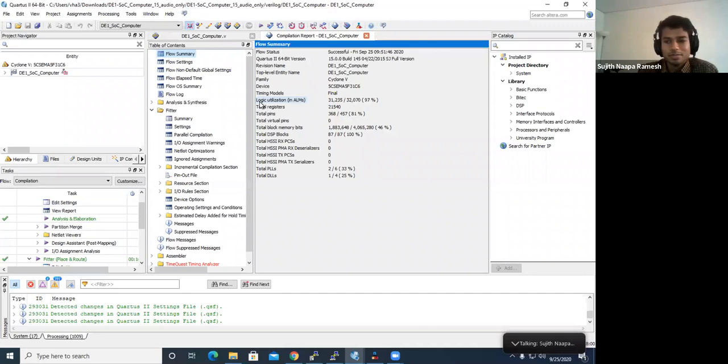Thank you. And like I said, we'll talk next time about a strategy, a way to think about this, perhaps parallelizing in one dimension of the drum and serializing in the other dimension. So updating a row in parallel and then serially walking up the drum as far as you can get before the next audio sample comes. It's a strategy to think about, but you can do whatever you like. You can tile these things, you can have whatever arrangement that you want, but you'll need some combination.